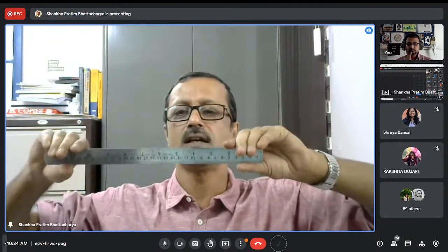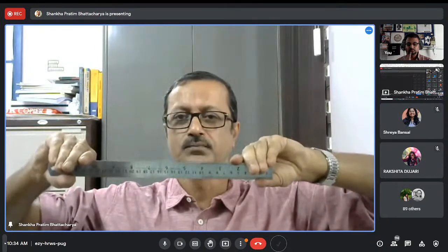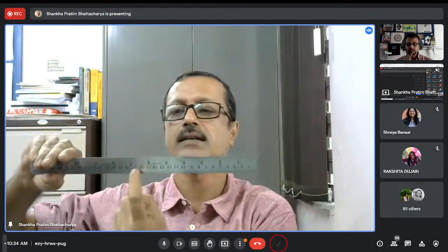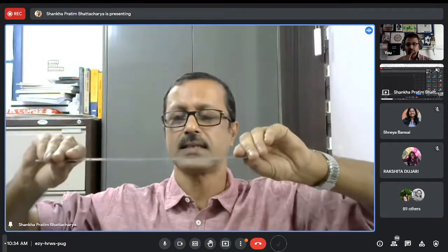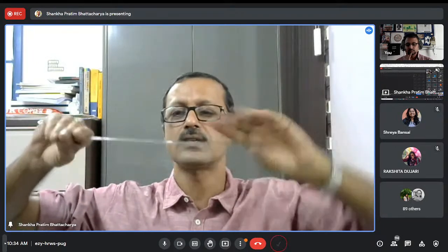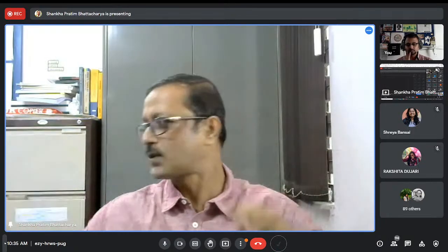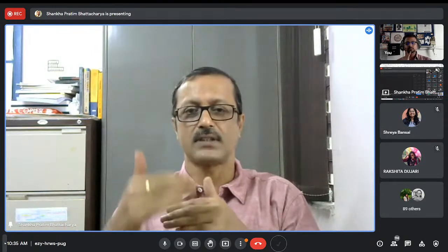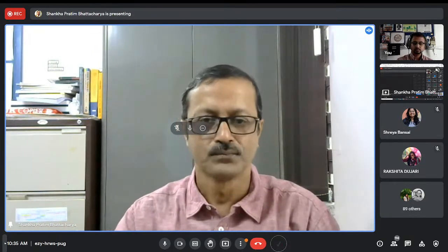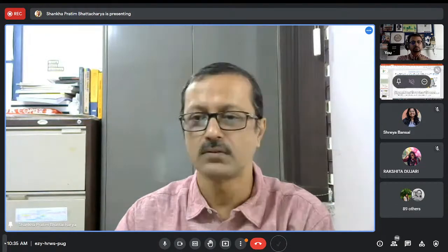Why? Because the force or the moment I am going to apply now encounters the larger depth. Otherwise, in this case, if the moment or force I am applying is on a smaller, very tiny depth, it is very easy. So depth plays a role. And actually, it is not just the depth, it is the moment of inertia that plays the role. So that is why, again, I'll go back to this PPT.